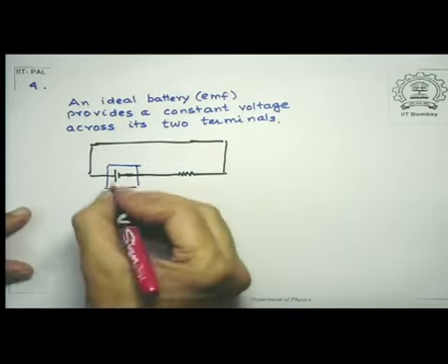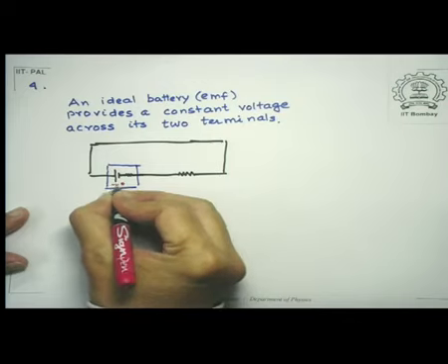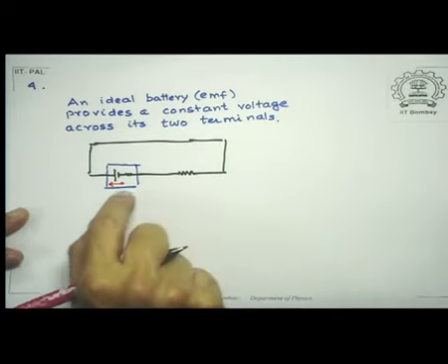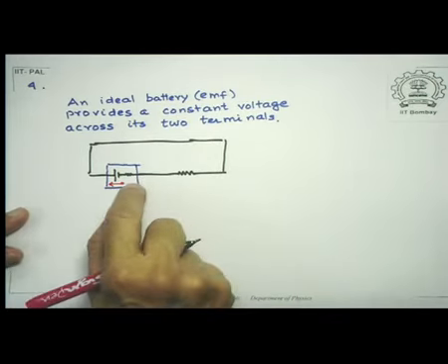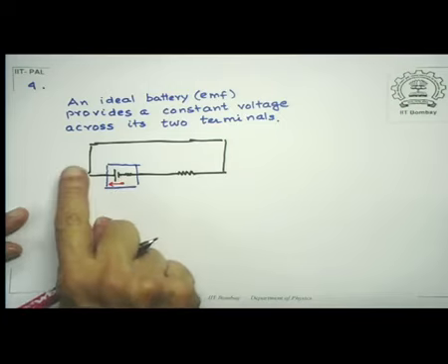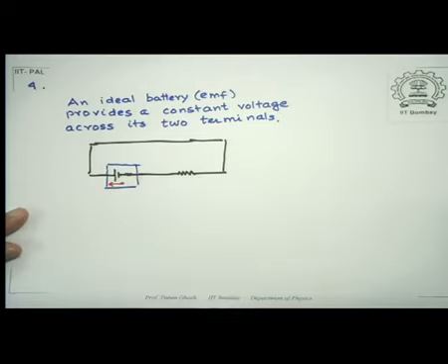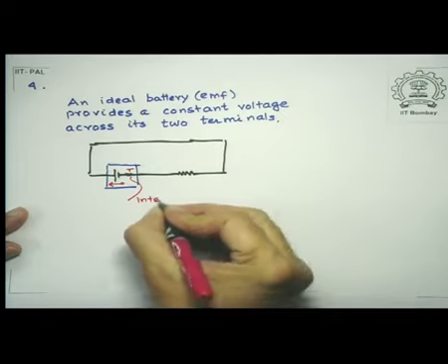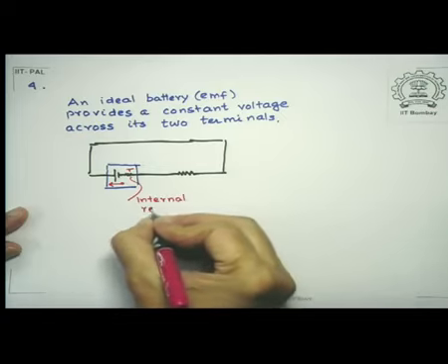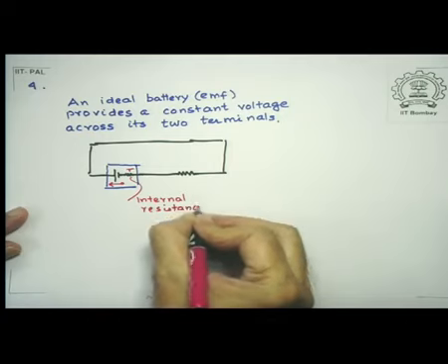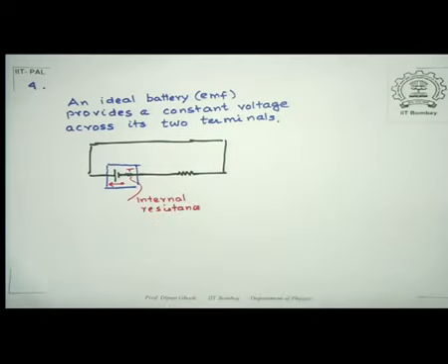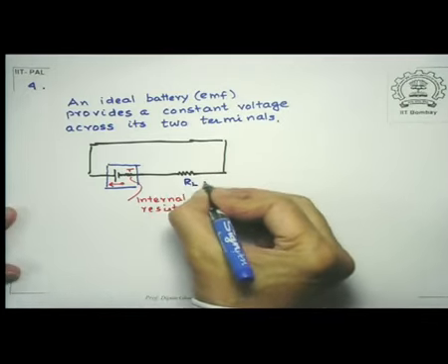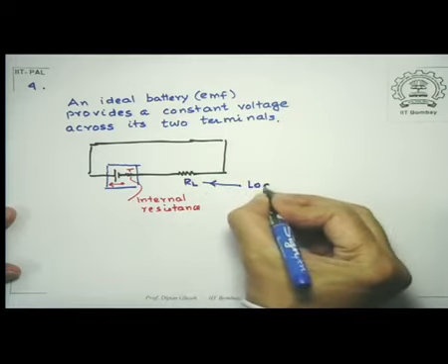What is frequently done in electric circuits is to do this type of a mark with a little circle at the base to indicate I am talking about EMF direction, that is the direction in which the voltage increases from the negative terminal to the positive terminal, and there is a little internal resistance there. So this is your representation of the battery. The outside circuit, RL, is what is known as a load resistance, because that is the load that the circuit bears.